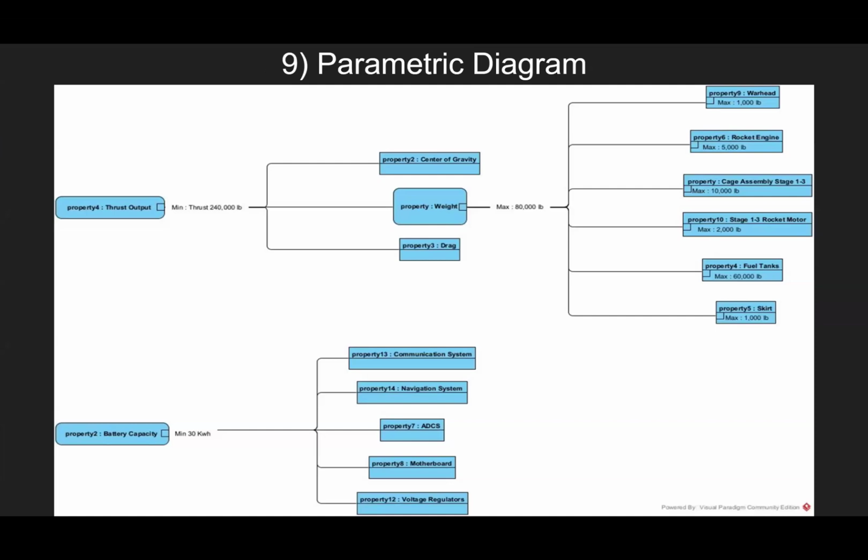And then the last thing with the parametric diagram was just, I think the hardest part overall is reliably getting that missile up. Stage 1 should be the hardest part of the flight. So just trying to make sure that you balance how much thrust you can actually output and how much you weigh. From what I saw, it looked like you had to have about 3 times the thrust capability of your actual weight.